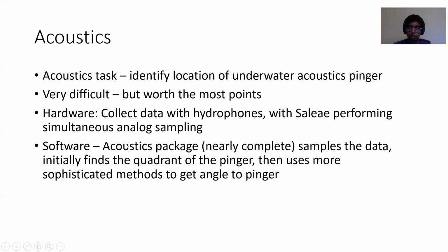In terms of software, we have the acoustics package, which is not yet in master, but we're nearly done with it. It samples the data and makes a guess for where the pinger is by finding the quadrant of the pinger, and then uses a more sophisticated technique to get the actual horizontal angle to the pinger, or at least what we believe to be the correct horizontal angle.